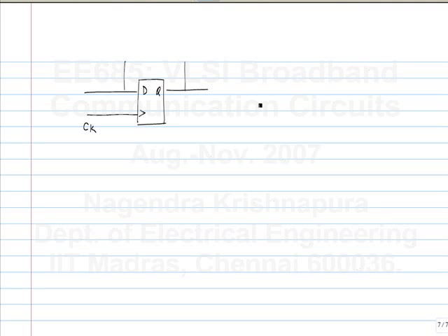Yeah, so you will get some error in the phase measurement. You will get a noise in the phase measurement. But you are still measuring. I mean, your clock is jittery. So you are measuring the phase difference between the data and the clock correctly, right? But the clock is jittery. If the jitter is too much, you have to do something to the clock source. Okay, this is not a problem of phase detection, right? It's just that your clock has jitter and your measurement includes the jitter. Okay?